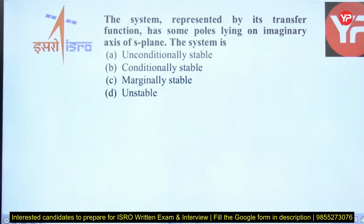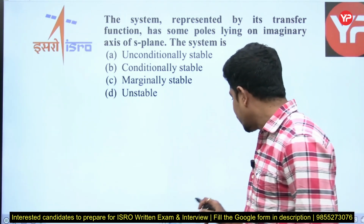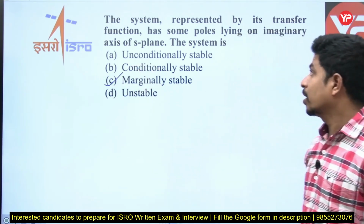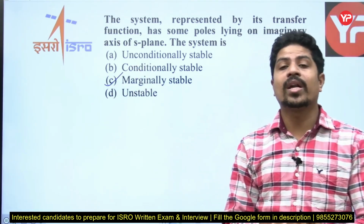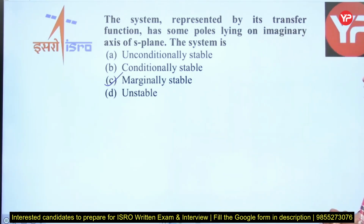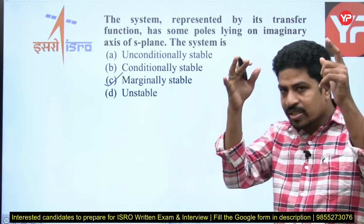If the system represented by its transfer function has some poles lying on the imaginary axis of the S-plane, then the system is marginally stable. If there are poles on the imaginary axis without repetition, he did not mention with or without repetition, but we are taking it as without repetition, the system is marginally stable. If he says that poles are repeated on the imaginary axis, the system is unstable.